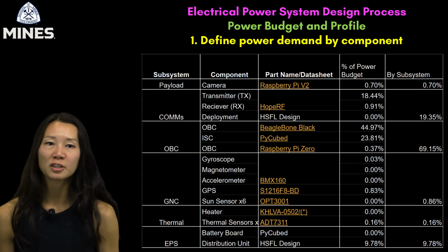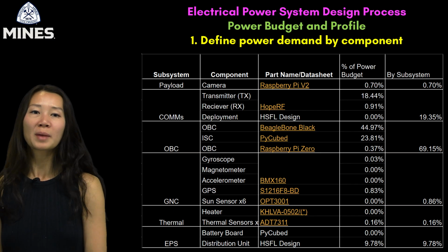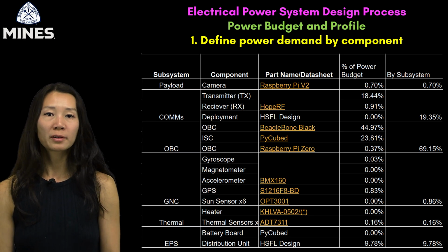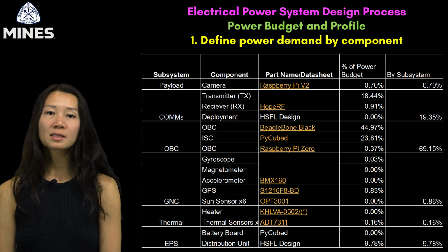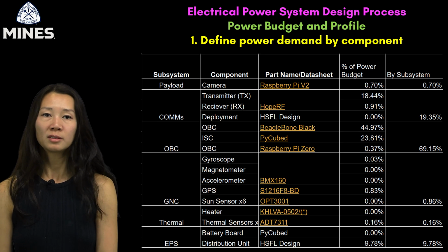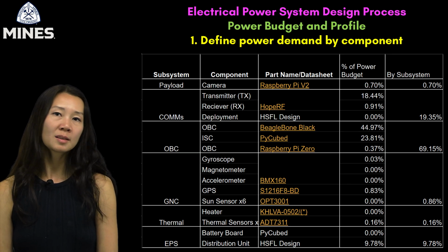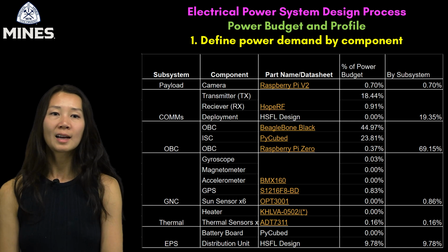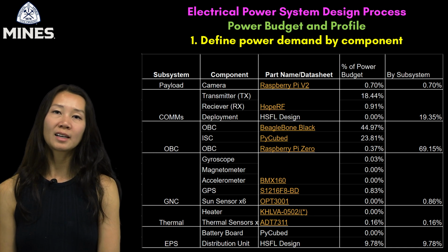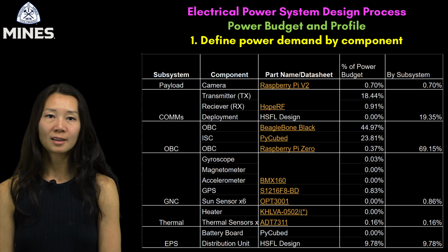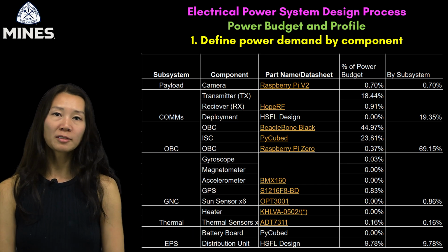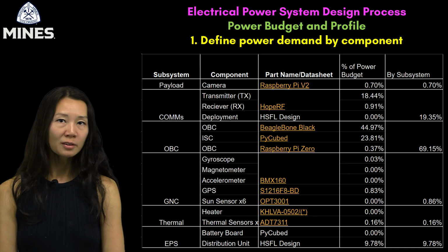design a power generation, energy storage, and power distribution solution given some design drivers, such as power consumption of other subsystem components, anticipated power possible given the environment, and your concept of operations. I'm going to use this template for a design class I taught and a satellite I designed at University of Hawaii as a case study, which generated all of the numbers and descriptors you see here. You'll have to do this for your assignment, so take note of the process.